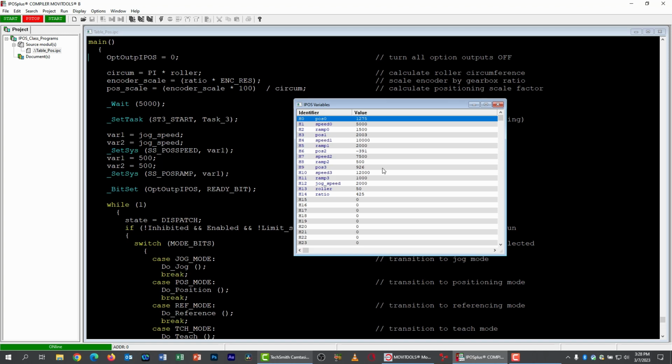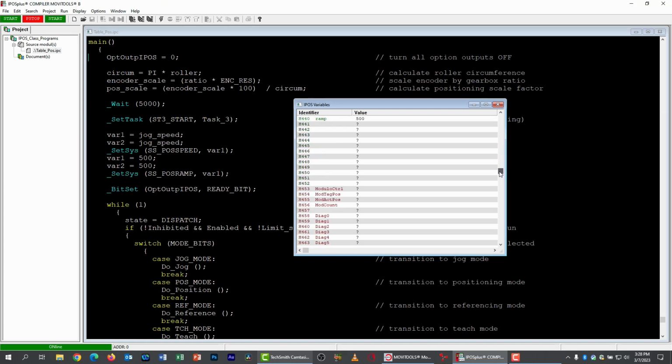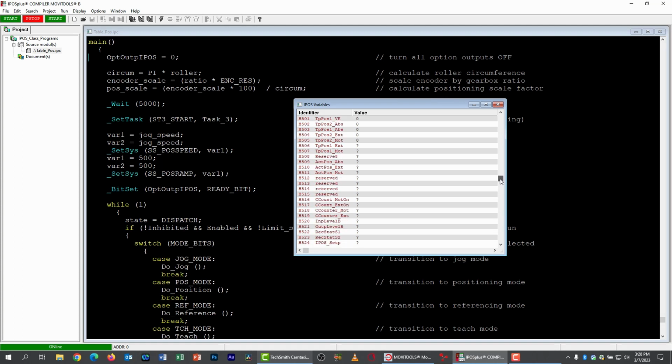Now, if I want to confirm that, I could manually calculate from active motor position this value. And I'll just remind you that the system variables are shown in red. And I'll find active motor position right here. It's H511. And it says that the motor's current position is 102,730 increments.